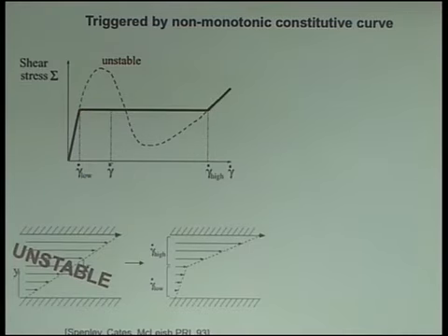And then force balance considerations tell us that in this limit of creeping flow, the shear stress has to be uniform across the gap, and so common to both the bands. And so as we track this average applied shear rate to the sample as a whole through this shear banding regime, the shear stress, which as I've said is common to both the bands, stays constant, as does the shear rate in each band, and the only thing that adjusts is the relative volume fraction of the bands, in other words the position of the interface, to satisfy the increasing overall applied shear rate. So that looks a bit like a lever rule to someone from the phase transitions community in physics.